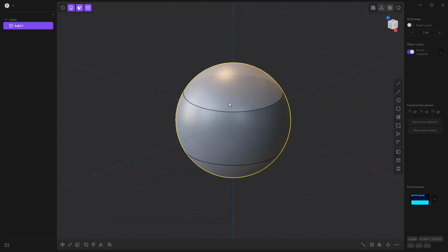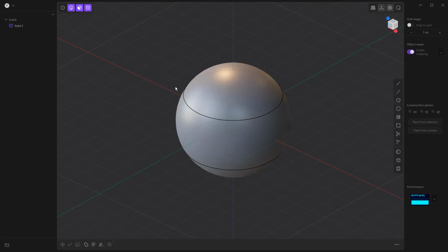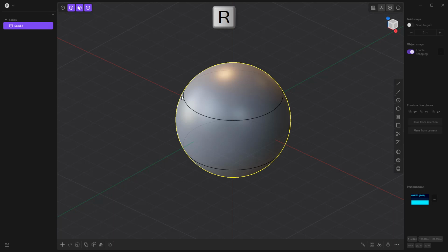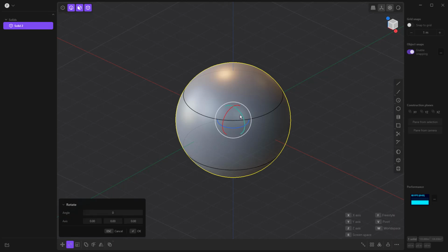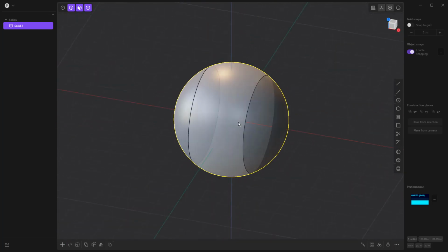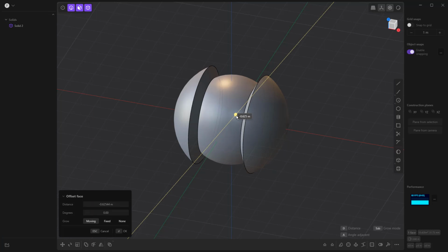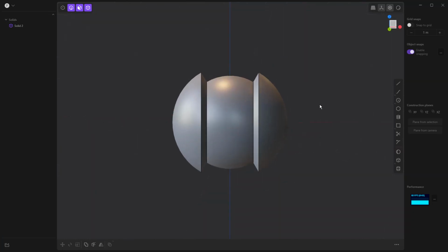Now, these are facing the wrong way, and part of the isoparam thing with the sphere is that it's only going to go halfway in one direction around Z because it's actually revolved. So we're going to select the entire object, hit R to rotate, and rotate about Y: Y on the keyboard and 90, hit Enter, then right-click to accept. Now we can take this centerpiece and scale it down to whatever size we need. You can see we've started to make our rolling droid shape.